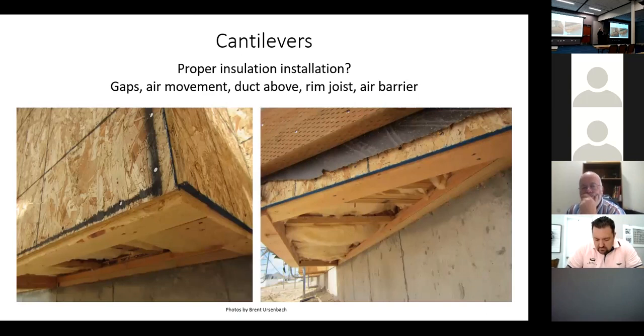This house I'm in now, we bought it in August. October came around, we had a cold day, and the wind was blowing. I walked downstairs in bare feet across the hardwood floor in front of the bay window, 12 feet from the bay window, and the floor was ice cold. Why? Because we had a bay window, kind of like this, with just aluminum soffit material on it. It wasn't vented soffit, but it was soffit that was cut a half inch short so it would fit in the J metal and not bind up. And the air went right through it. When I stripped it all off, what color was the yellow insulation? Black, because of all the air that was moving through it.